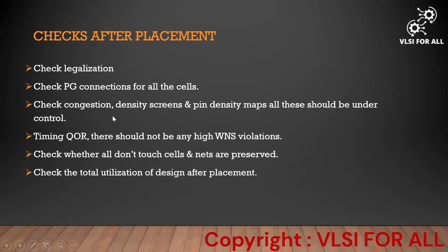And check the PG connections for all the standard cells, how the PG connections have been made, and they have to be checked accordingly. And we have to check the congestion and timing as we saw earlier. For congestion, report_congestion, and for timing, report_timing. If there are any congestion-related or timing-related errors, they will be popped out here.